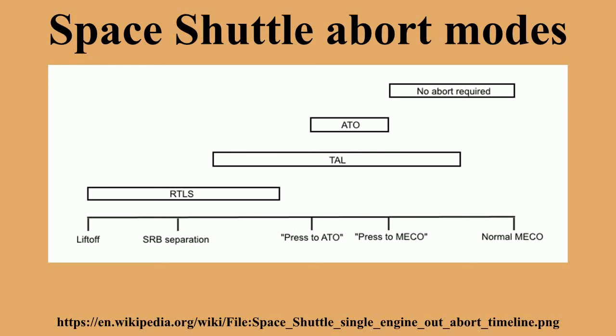Major modifications required a shuttle, likely taking several years. During much of the period the vehicle would be unavailable. Cabin ejection systems are heavy, thus incurring a significant payload penalty. Cabin ejection systems are much more complex than ejection seats. They require devices to cut cables and conduits connecting the cabin and fuselage.